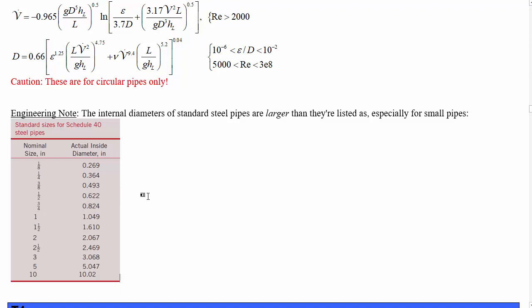and so on. And in addition to that, when manufacturers found better materials and better processing techniques and were able to make steel pipes have thinner walls and hold just as much pressure, they left the outer diameters the same and ended up increasing the inner diameters further from Briggs's original specification. So we're left with a Schedule 40 steel pipe system where the actual inner diameter is well defined. It's just nothing like the label.